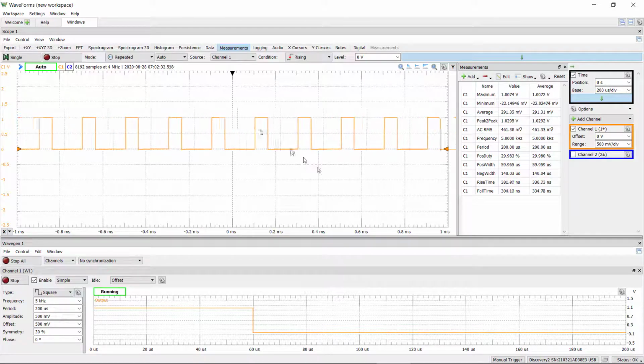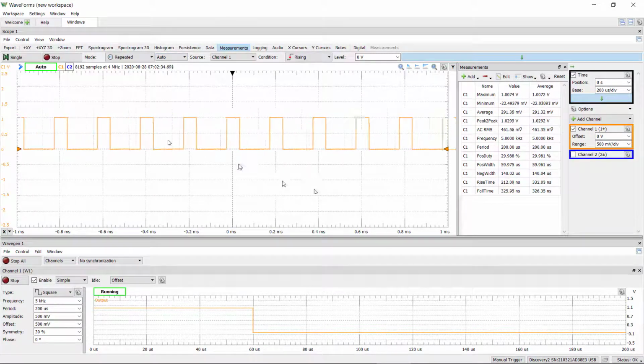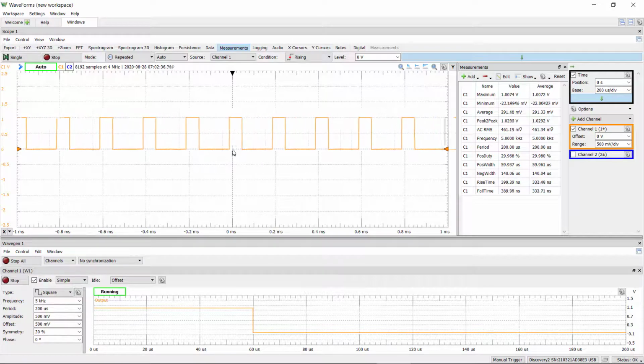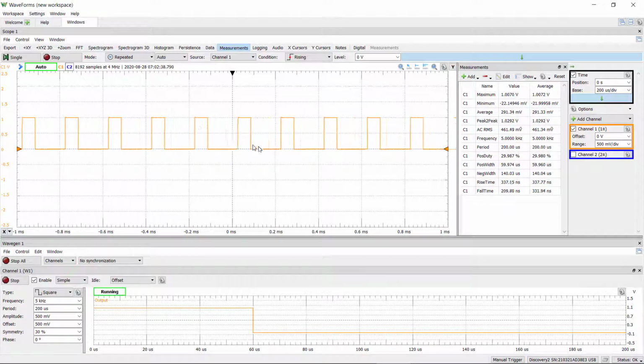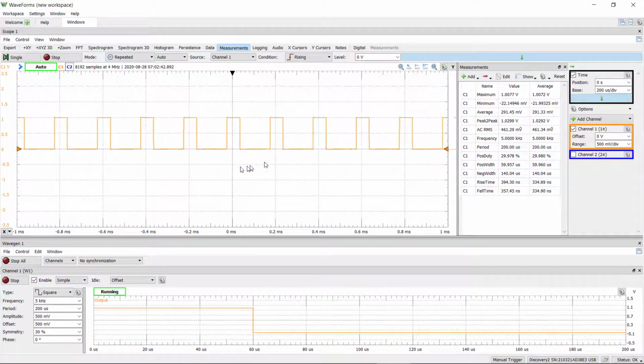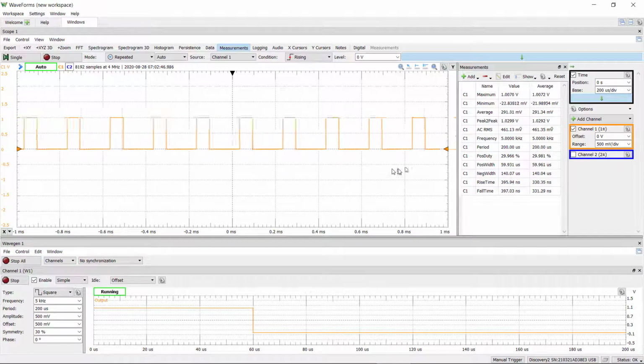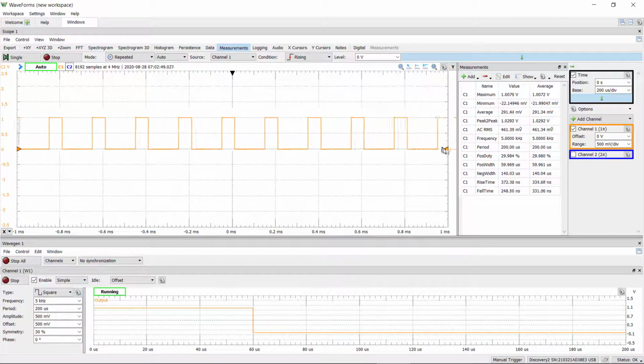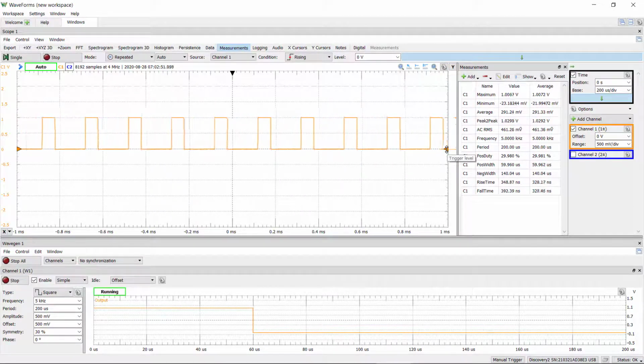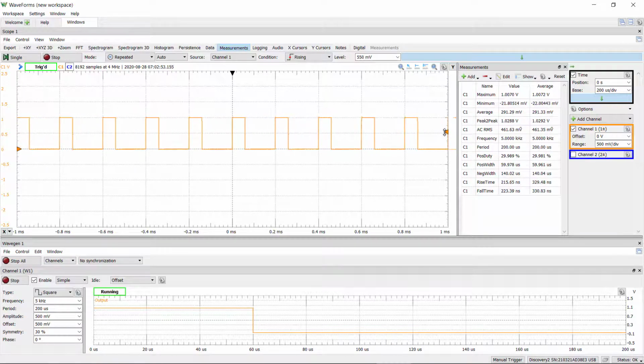How come? That's because I'm on auto, which is good. I'll see it even if I don't get a valid trigger signal. I'm not triggering it based on the voltage of the waveform coming in and the pattern. I'm triggering it because of time. I don't have a trigger signal coming in, so I just trigger anyway. That's because my level went slightly below where the trigger level is. I need to adjust the trigger level, and now we're triggering.